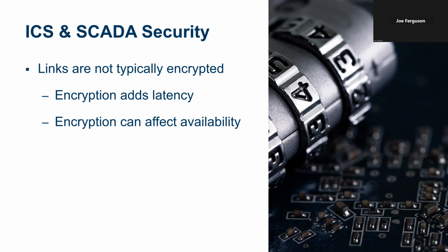So these breakers are typically rated in how many power cycles, 60 hertz cycles, it takes to open up that link. So let's say you have a breaker, or a relay, that will disconnect power in a single cycle of 60 hertz power. That's about 16 milliseconds, right? So you're saying that if I detect the fault and send a command, you'll be turning off power in 16 milliseconds. But now I want to add encryption to that. Let's say that adds an extra millisecond or 2 or 3 of latency just to add the encryption and check the encryption on the other side before taking action, right? That's a fairly large percentage of that 60 hertz cycle, right? So we're talking easily adding another 20, 30, 40% of that delay just to add encryption.